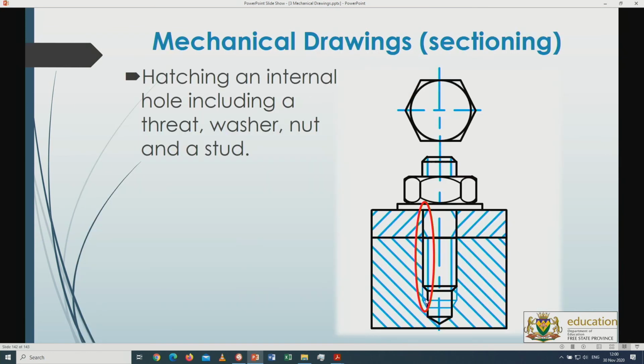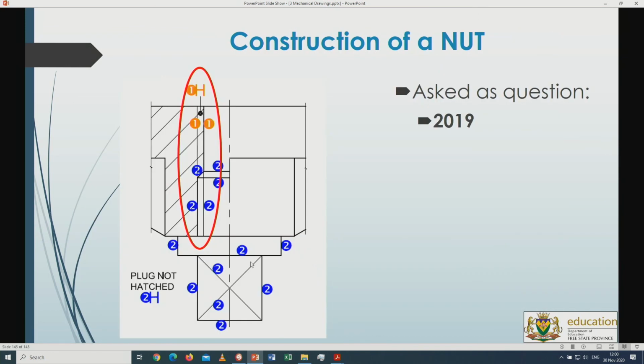Right, hatching is important, not to go over the hatched lines. Here you can see the sump plug that has been turned in, no hatching on the side. From there further onwards, the hole is still open and the thread goes up to the end, so therefore the hatching goes in there. So this portion and that portion.